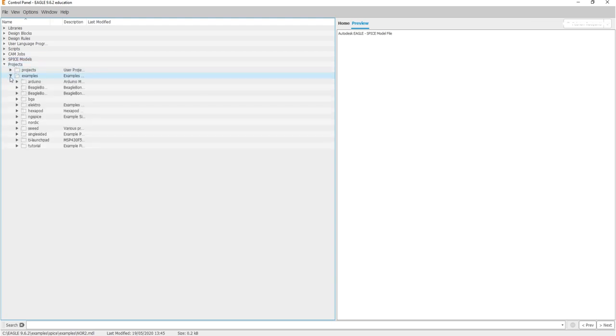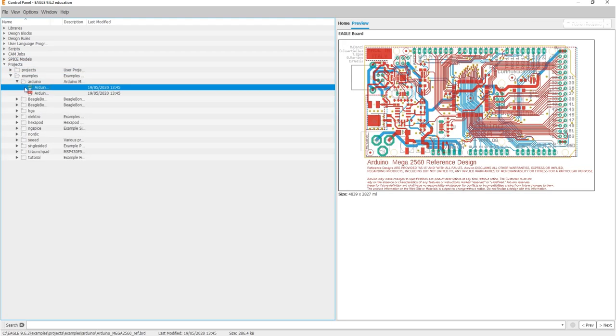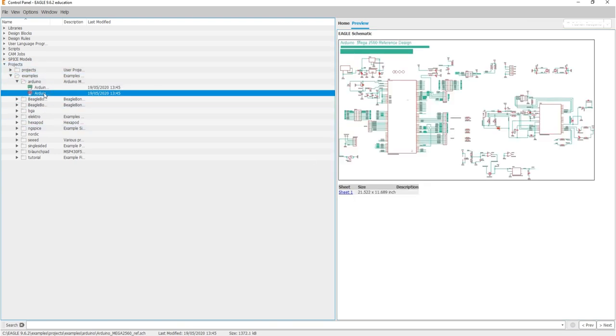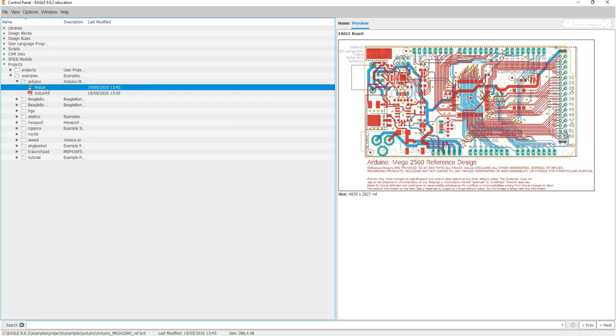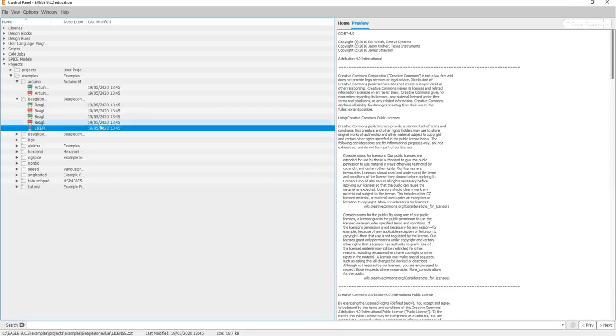The next one is project. A project usually consists of a folder which represents the project by its name and the project's configuration file, eagle.epf. The folder usually contains all files belonging to your project, for example, schematic and board files, special library files, script files, and so on.